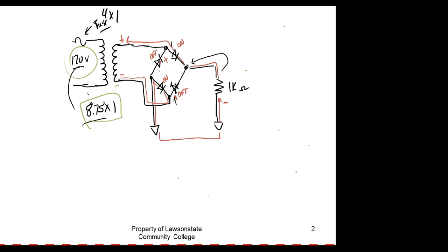Okay, we're okay. How many diodes did it go through? Two. How much voltage are we going to lose on V peak out? We're going to lose 1.4 volts because they're in series with each other, right? You understand? Everybody okay?